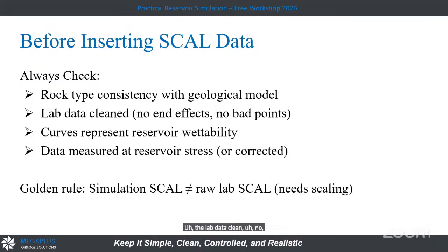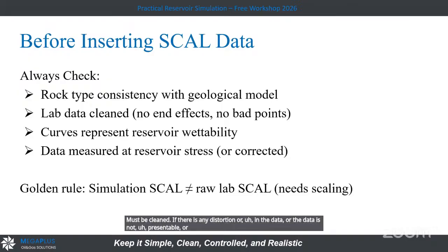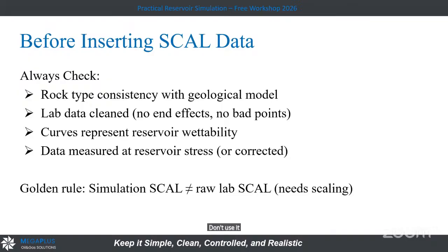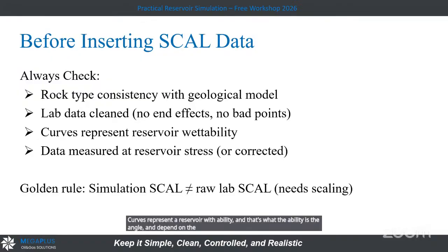No, the lab data must be cleaned. If there is any distortion in the data, or the data is not presentable, don't use it from the beginning, because it will get you into very big problems after that. Curves represent reservoir wettability, and that's what the wettability is, the angle, and it depends on the interfacial tension forces that